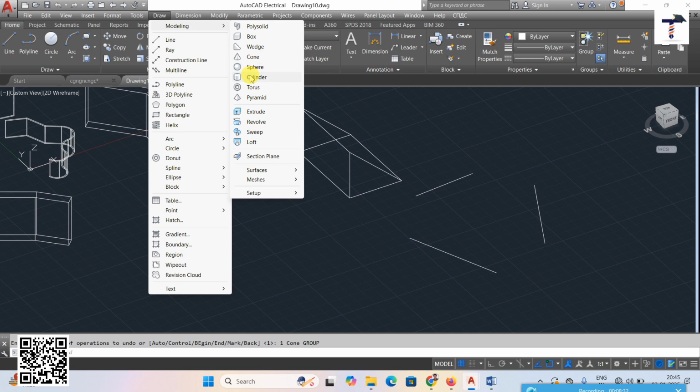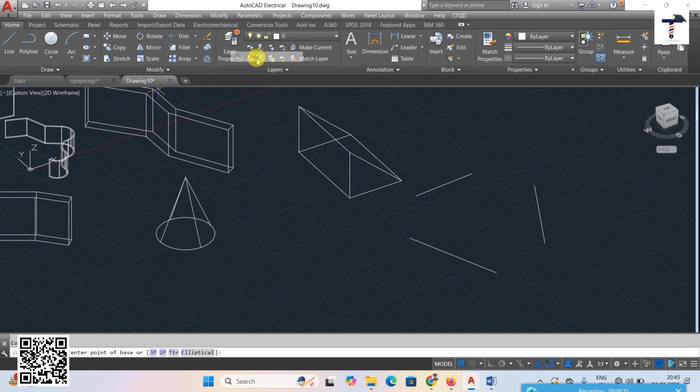Next, also a cone, the elliptical one. Elliptical means you select the endpoint of the axis and select another axis, and then you can choose the major axis or minor axis. Okay, for the second axis, select this one and then give the height. So that is the elliptical cone. Clear?